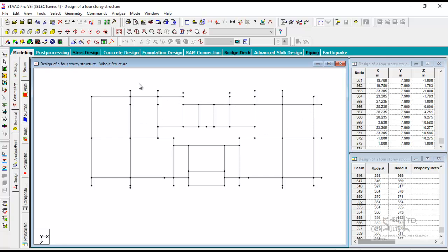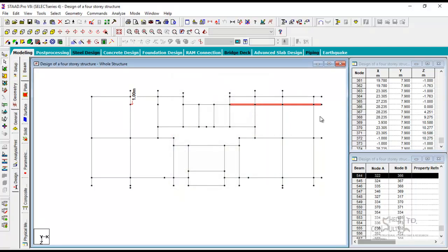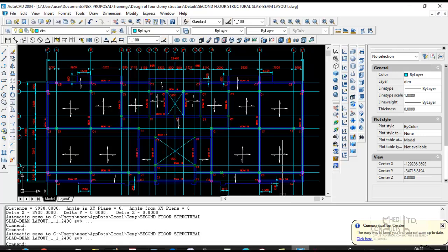How do I do that? Just the same way I have done this. Distance is 1 meter. Okay, I just select this and that, and then copy and paste. -1 meter. It takes it up for me. I delete this one that it created. I then move this one rightwards from here to here as well, 1 meter. You can always back check the coordinate. X is 27.235. Here is 28.235. 27 minus 28, that's 1 meter. Okay, you move that as well rightwards by 1 meter.